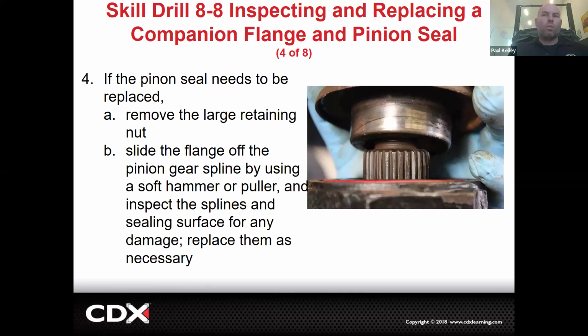Now, this is the scary part. When you over tighten it, you're crushing this part called the crush sleeve. Then when you loosen it, that crush sleeve is very loose and those bearings are actually sloppy. So that whole pinion is going to be moving and rocking around. So don't over tighten it, because if you do, you can't just loosen it. But he was kind of like, oh, whatever, I'm gonna send it. So he loosened it and sent it.